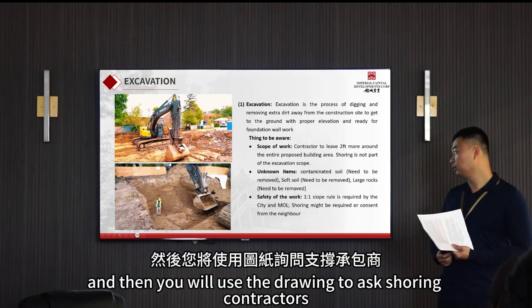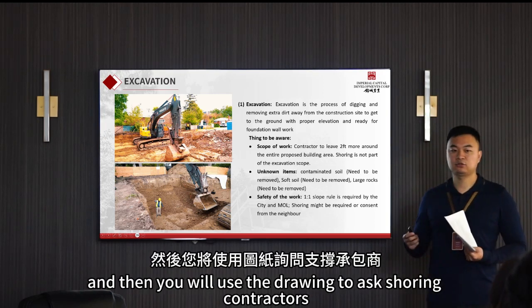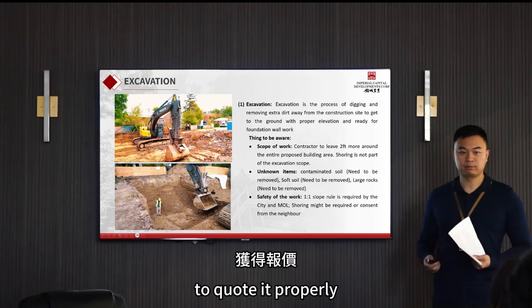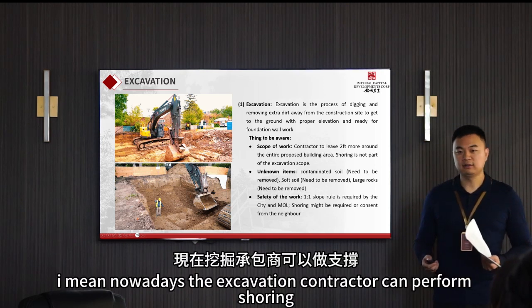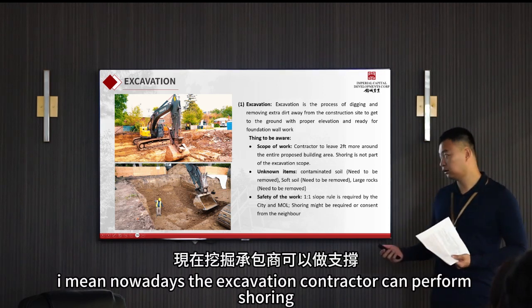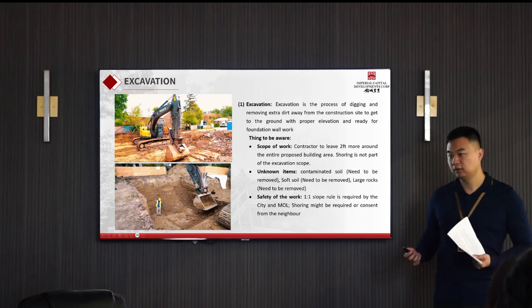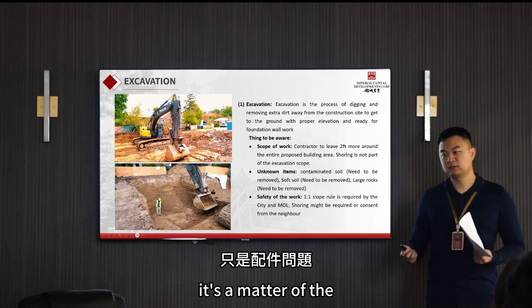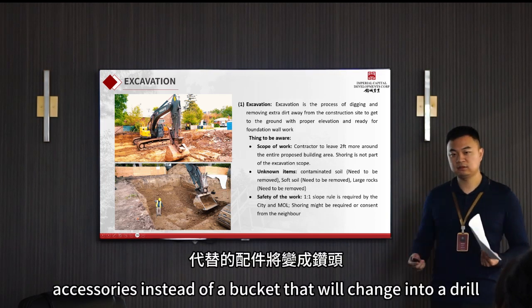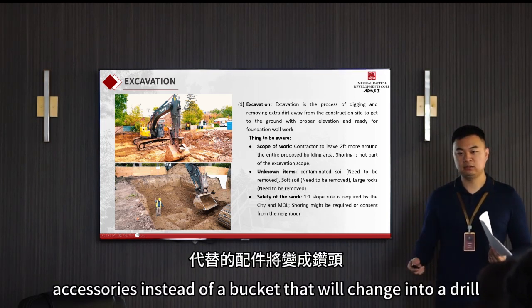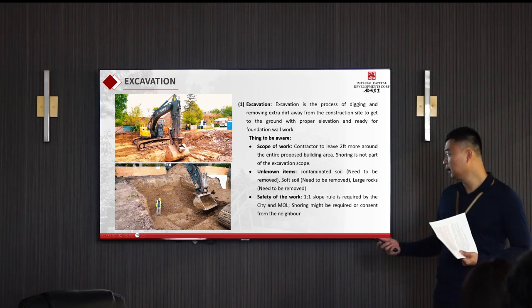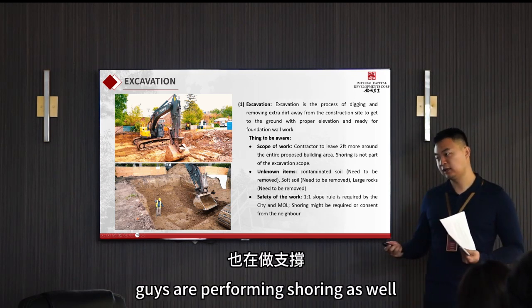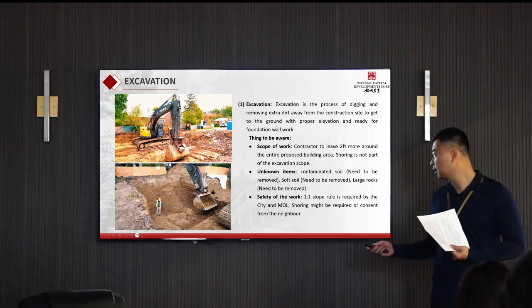Then you use the drawing to ask shoring contractors to quote it properly. Nowadays, the excavation contractor can perform shoring as well, because the machine itself is the same. It's a matter of the accessories. Instead of a bucket, they will change to a drill. So a lot of the demolition excavation guys are performing shoring as well.